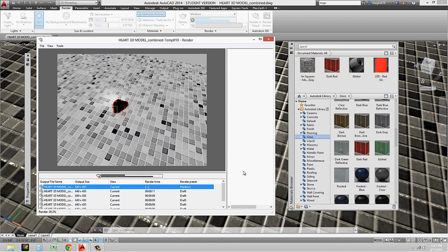This is going to take more. And you might find that your materials might not be reacting to the light so much. It's not really about adding more light. It's more about the materials reacting to the light. So I always find that an inverse to how traditionally you start to think about rendering, materials and lights. In this case, it's not so much about adjusting the lights. It's more about adjusting the materials.